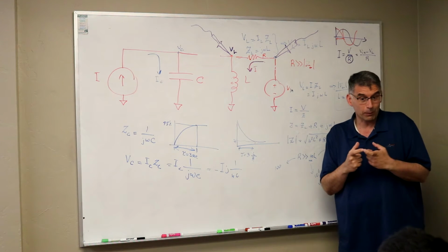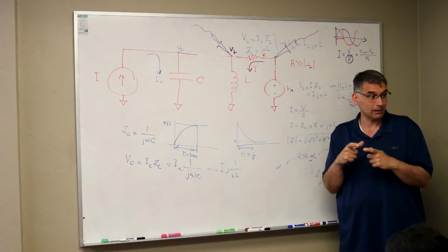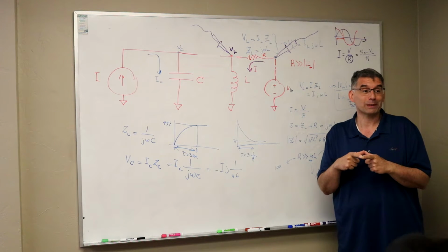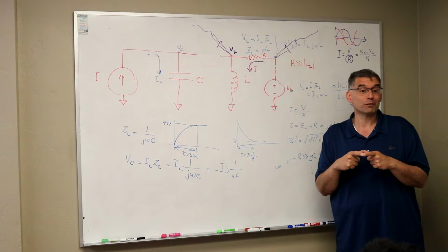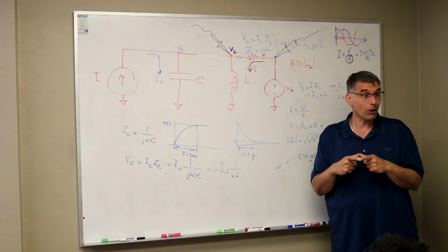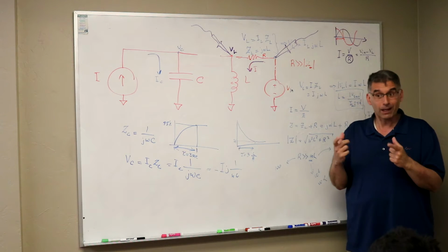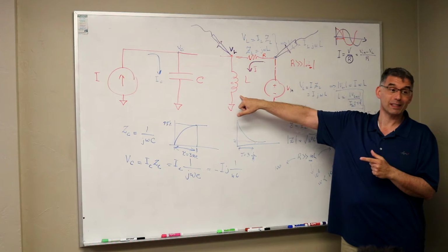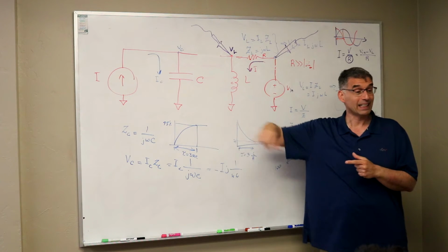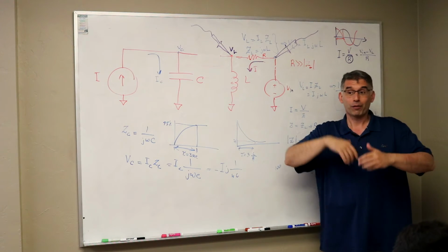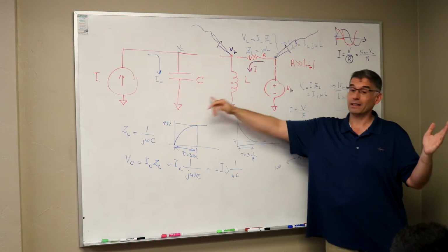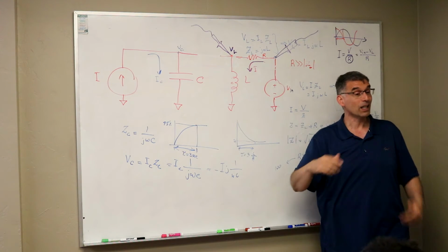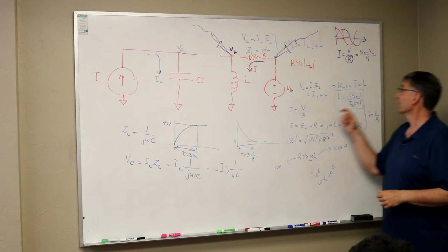Remember at the beginning we started with an LC circuit when we had the inductor and the capacitor. And Mr. Winters was saying that at a certain frequency that impedance becomes 0. It's because, remember, for this one the voltage is leading, for this one the voltage is lagging. At a certain frequency the voltages on this one and this one are 180 degrees out of phase, right? Because this is 90, that one's 90.